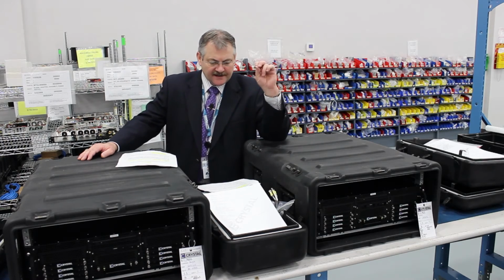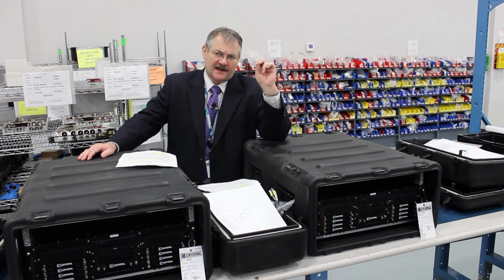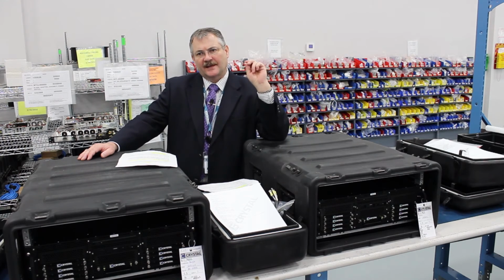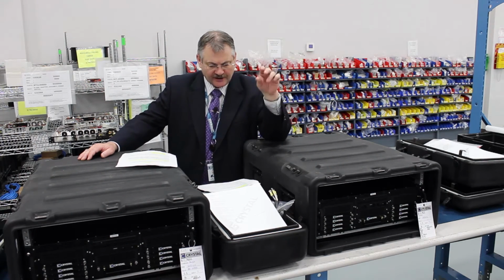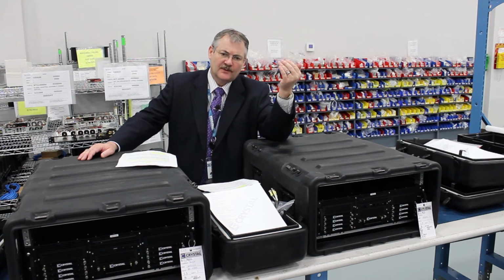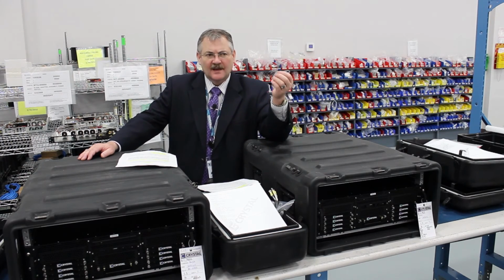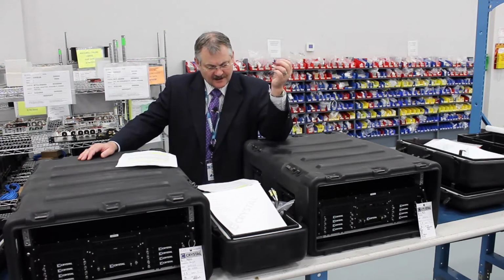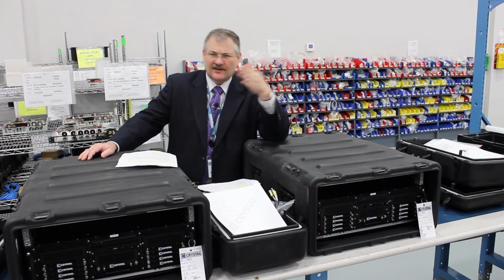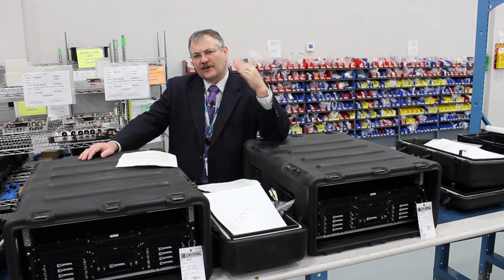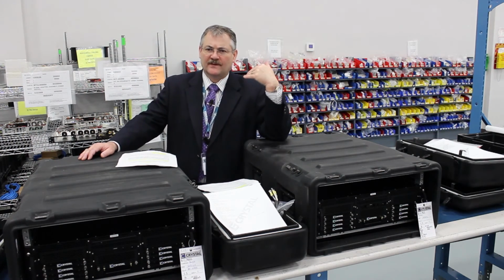A couple of things that you want to make sure that you specify during this testing are the test temperature, the transition duration, and how long you want to have the system at that temperature, or the dwell time, and then the number of cycles. Transfer times, in terms of door open, door closed, and then how often you are going to actually check the performance of the unit.